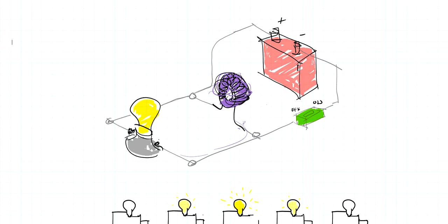So let's say we have this circuit, with this source, inductor, and this lamp. If we turn on the switch, then there is a flow of current. At first, initially, there is no magnetic field yet. Once the current passes through this coil, some of the current will pass across this lamp. So this lamp will light up, and the inductor will start building up its magnetic field until it reaches its maximum.